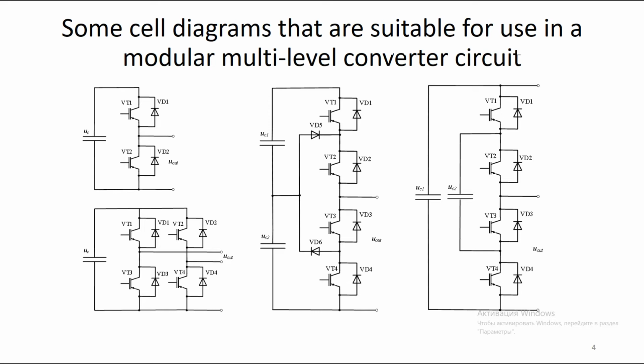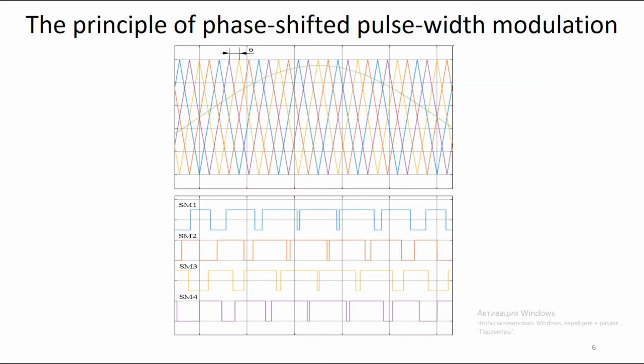To obtain the switching signals of the switches of the converter modules containing N modules per arm, the phase-shifted triangular carrier signals are generated to control the upper half of the circuit, and the same signals to control the switches of the lower half of the circuit.